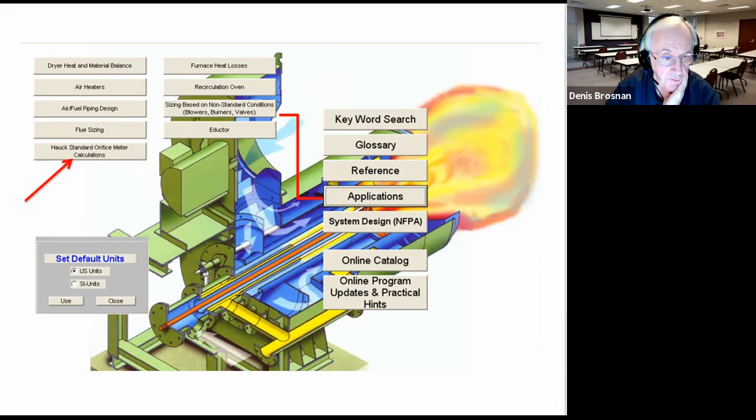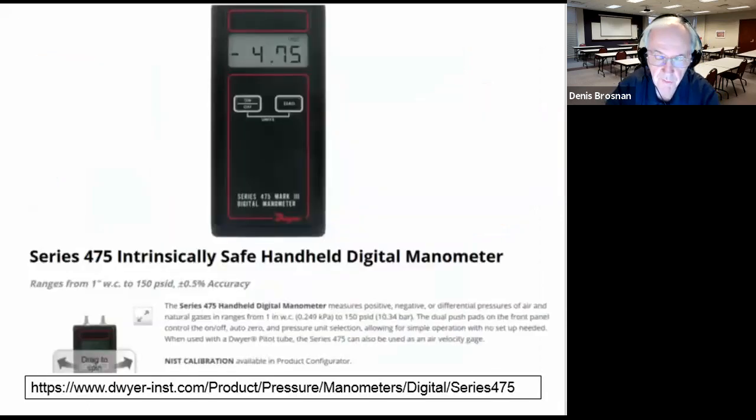Now, there's one other thing to say that's really interesting, and that is that you don't have to carry around U-tube manometers anymore. Folks make handheld digital manometers, so there's going to be an inlet port for a piece of plastic tubing to bring a pressure signal in, and an outlet port on the low pressure side will come into another place, and it's going to show you the difference in pressure. Okay, and those are what I think most people are using today.